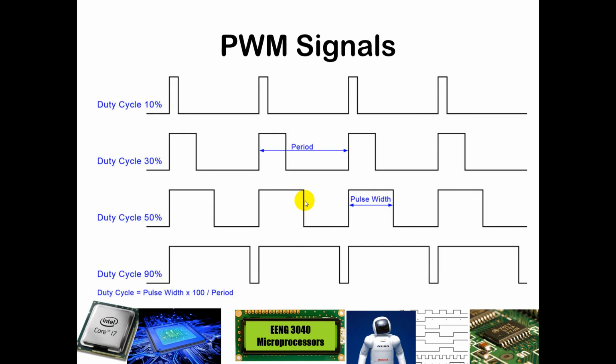So here you see some example PWM signals. A duty cycle of 10% would provide a fairly low speed motor movement, and so this would mean that the signal would be on 10% of the time and off for 90% of the time. Effectively what that means is the motor is not turning on and then going to a stop. It's not going to a stop when it's down here. It's just slowing down, and you see an averaging of how quickly it would go.